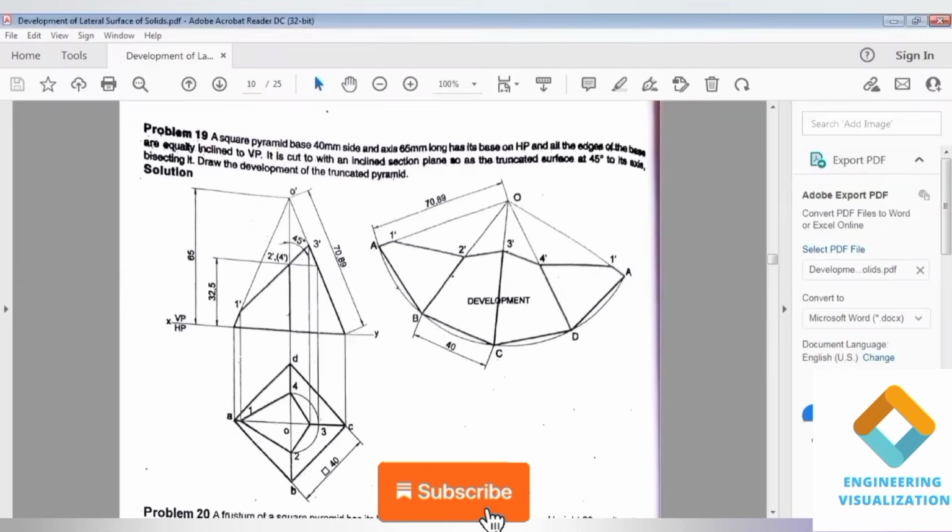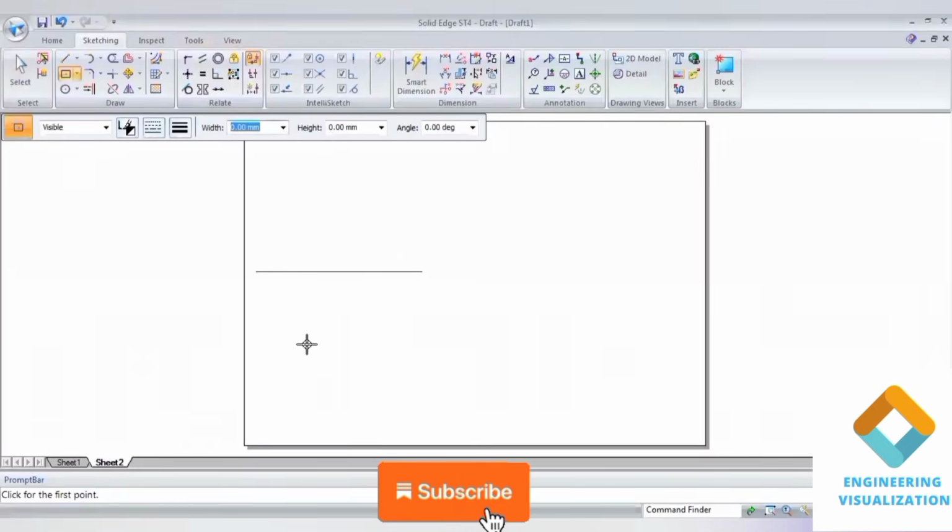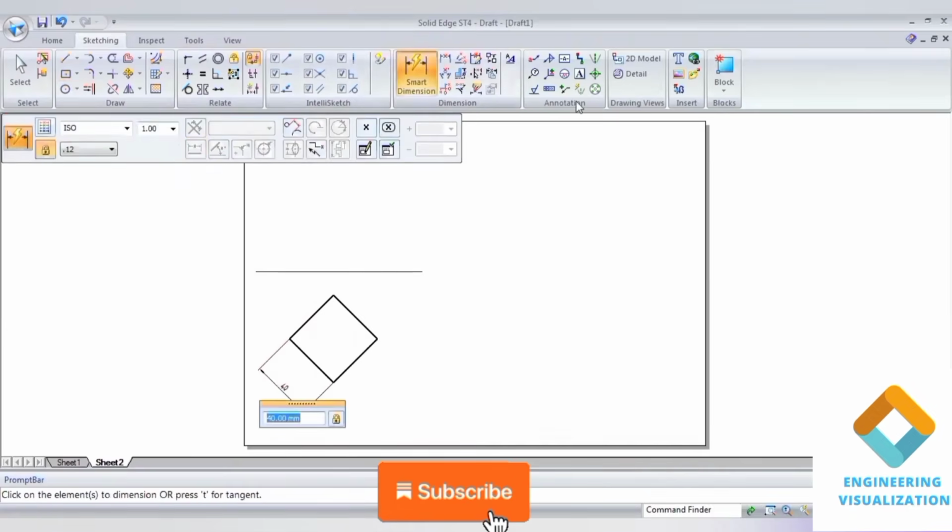So go to rectangle by center. Here the width and height we have to give, that is 40 and 40, and the angle will be 45 degrees. So this is how we construct the square with respect to the corner position. Show the dimensions, write down the namings for it.